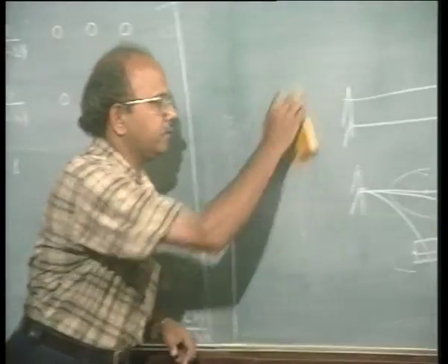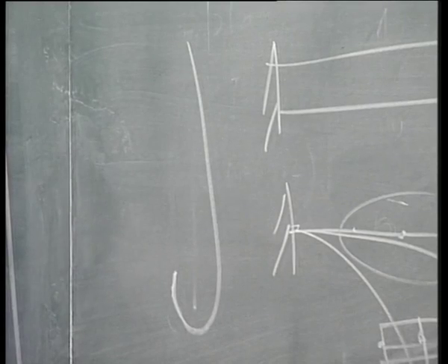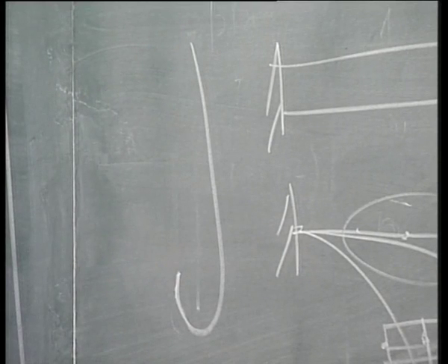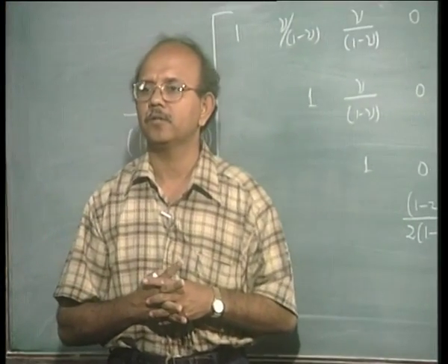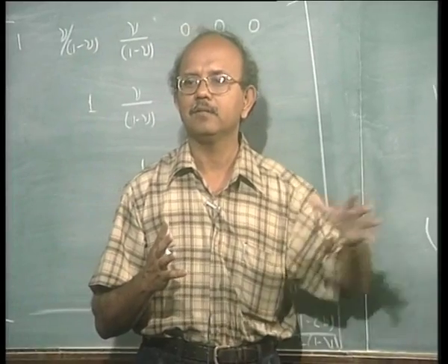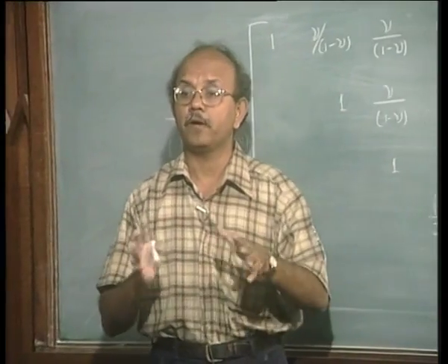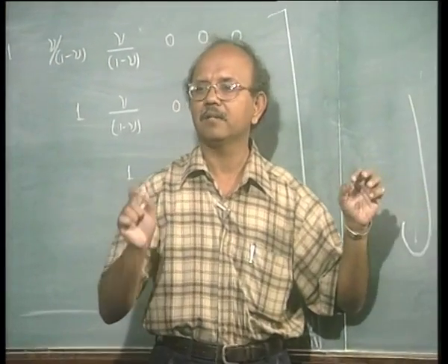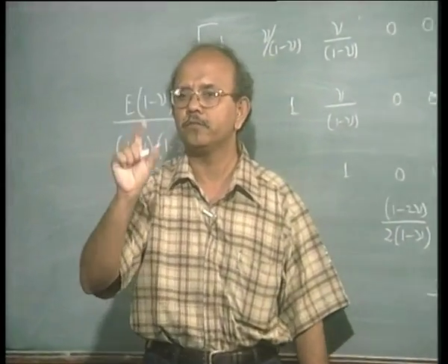In fact, the shape is something like that. Okay, this is a cross section. So the sheet is very thin and it has a cross section which is something like that. Now, when I model this sheet with a number of shell elements, at these joining places you can easily imagine that if I do not have a 5th degree, I am going to get into trouble and so on. If we have time, we will talk about shells later in this course. But right now it is important to keep in mind that the 5th degree of freedom is a question mark. Okay, what am I going to do with the 5th degree of freedom?